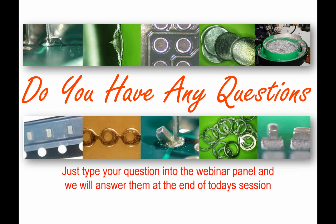Generally, I would say you need a flux or a flux reaction happening with the atmosphere you're going to use. There are a couple of applications in the market where you have no ability to use a flux or a reflow fluxing atmosphere. In those cases, you would have to use the cleanest of gold, noble surfaces that wouldn't have any oxide present on the surface, and then be reflowing in a no oxide environment, such as nitrogen, or even, if you could, a straight up vacuum, but gold to gold and as clean as possible. Okay, thank you very much for that.